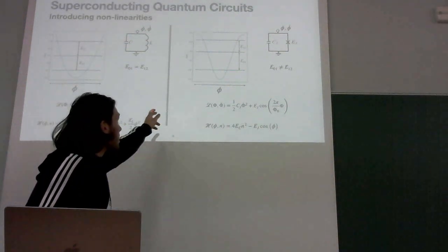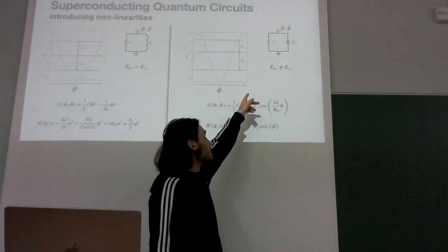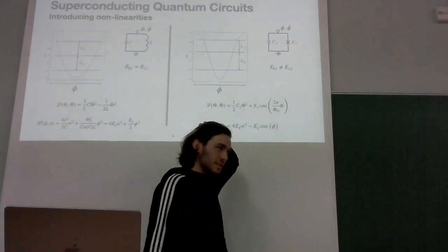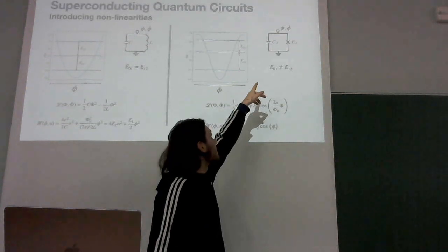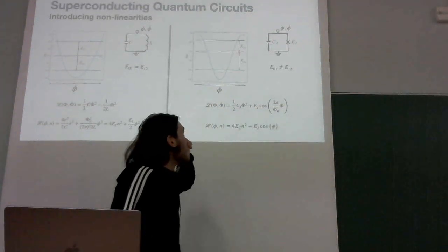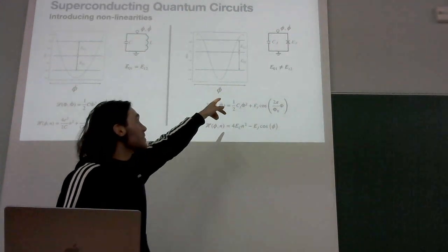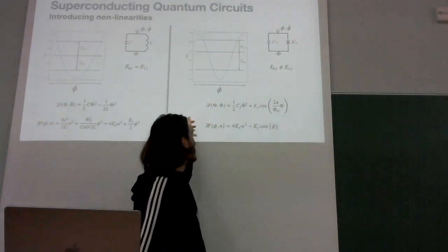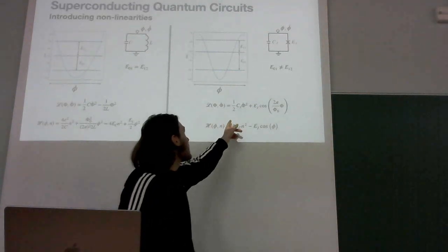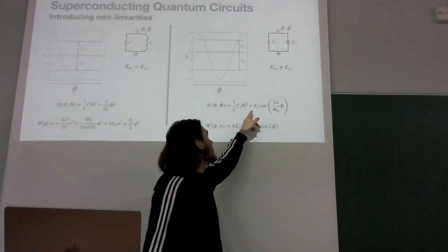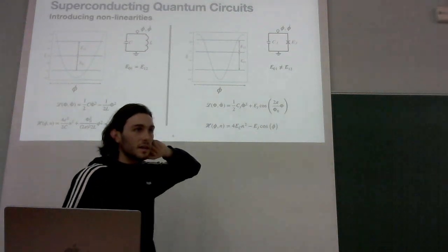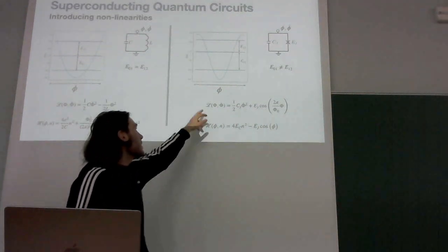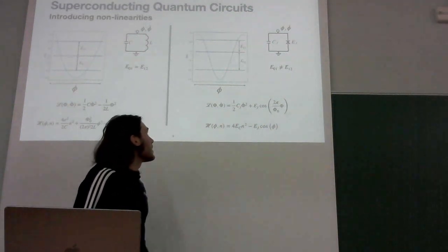In contrast, we can study one of the simplest but most used examples in superconducting circuits, which is the transmon circuit, which is essentially a capacitor connected in parallel with the Josephson junction. We can repeat the process with the diagram here, with a term due to the capacitance and then a term due to the nonlinear inductance, and perform the Legendre transform to obtain the Hamiltonian.